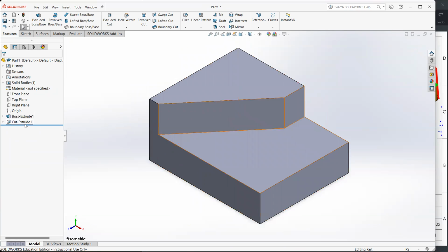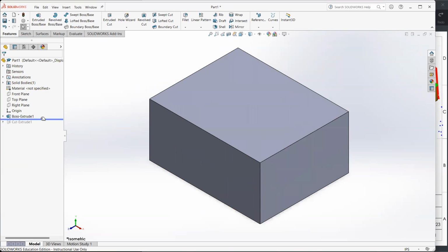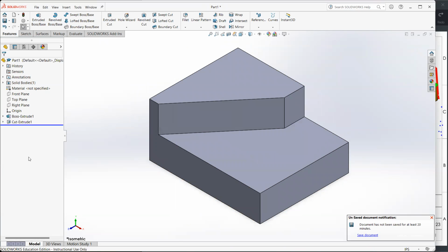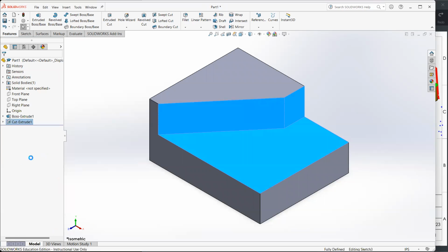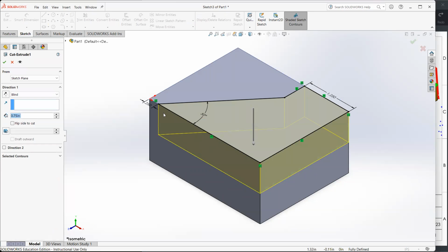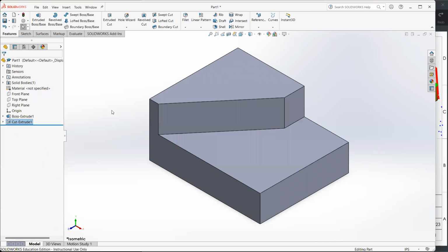As you see, while we are going into creating the part, we have the different features that we created in this features tree. At any point of time, we could simply drag upwards to cancel what we created, or we could go forward to see what we created. Also, if we right click, we could edit the feature if for any reason we created something wrong or we want to change the dimension of the feature.